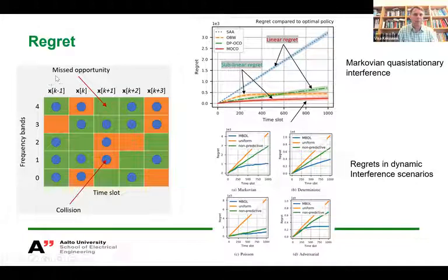And so here's an example where we have subcarriers on the spectrum and time instances, and the green subcarriers are those where it makes sense to use the spectrum. We choose those subcarriers and allocate powers to them. Of course, every now and then you make incorrect decisions, and you think that the spectrum cannot be used for sensing or communication, and then you miss the opportunity, which you can penalize. Or if you incorrectly think that the spectrum is idle and you use it for communication or sensing, but it's actually being used, then you will cause collisions and retransmissions and so on.